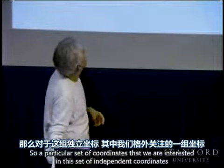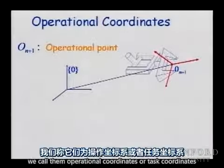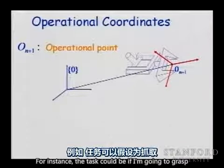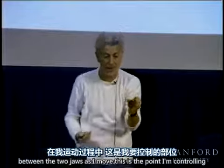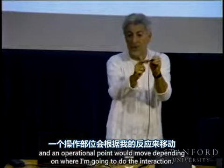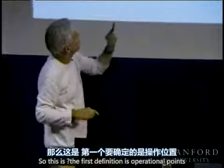So a particular set of coordinates that we are interested in is this set of independent coordinates. We call them operational coordinates or task coordinates. Essentially there we are looking at the operational point where the robot is acting, where we define the task. So for instance, if I'm going to grasp, the task is somewhere in the middle between the two jaws. As I move, this is the point I'm controlling. But if I have a tool, the task will be here, and the operational point would move depending on where I'm going to do the interaction. So this is the first definition, the operational point.